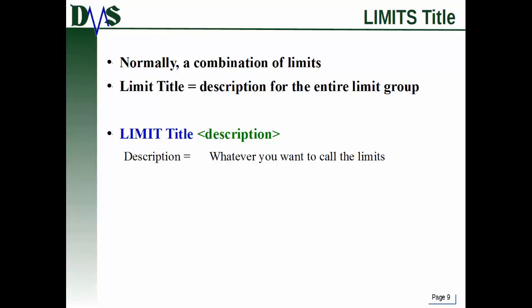It can be up to 25 characters long. Do not put quotation marks around this. No quotation marks here. Otherwise, those will show up in the title. So for example, if you said 46 CFR 170.173 was the regulation that required all the limits you're currently defining, you might type in here for limit: limit title 46 CFR 170.173. And that would be a very common thing to do. Now people know what regulation is being used to construct these limits.